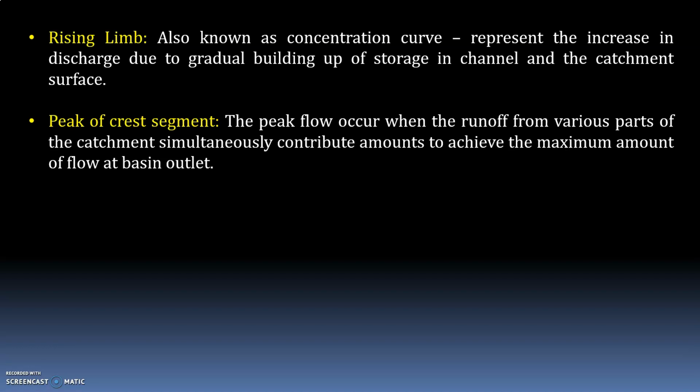The peak represents the arrival of the flow at the outlet from all the parts of the basin. For a large catchment, the peak flow point P occurs after the cessation of rainfall. The time interval between the center of mass of rainfall to the peak is controlled by the characteristics of both the basin as well as the storm.